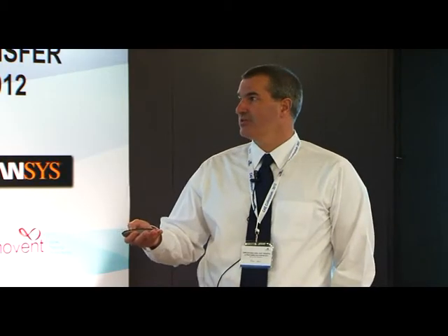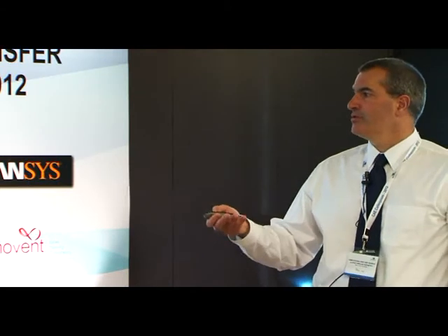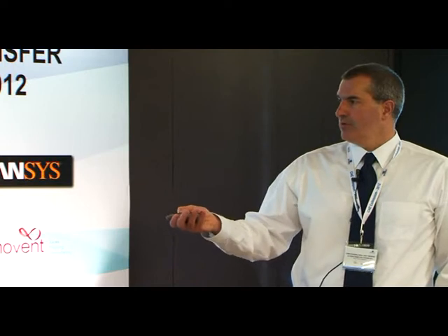The way that these things are designed, and probably every airplane you've flown on today has been designed using steady state methods, is that the design methodology takes a 2D axisymmetric representation of the flow through the turbine, and you use experimental data for film effectiveness curves, and you map that onto a thermal analysis model, and that's how you design your blade.